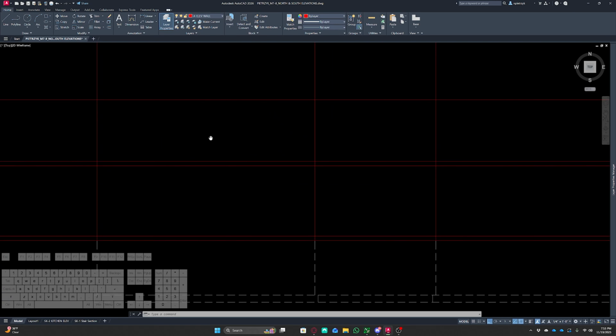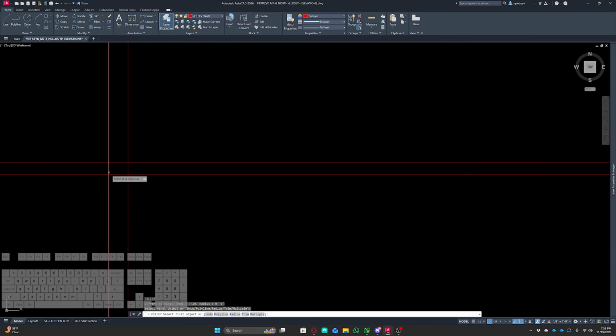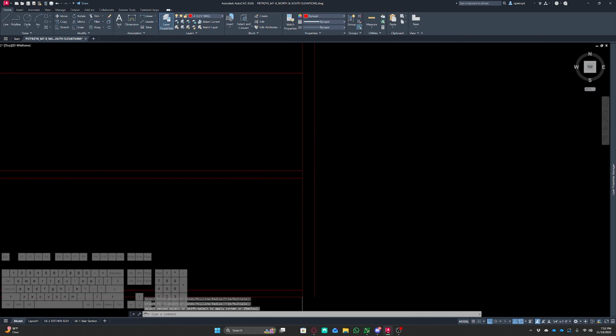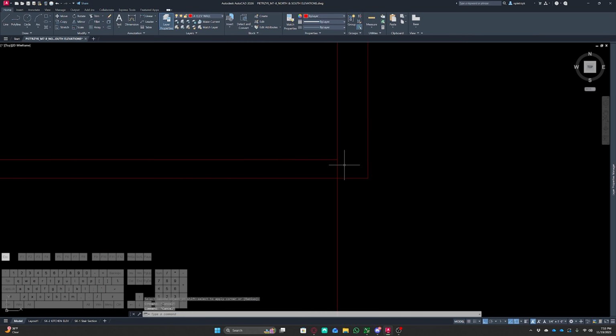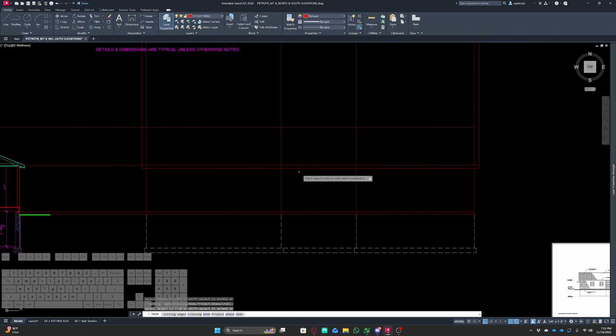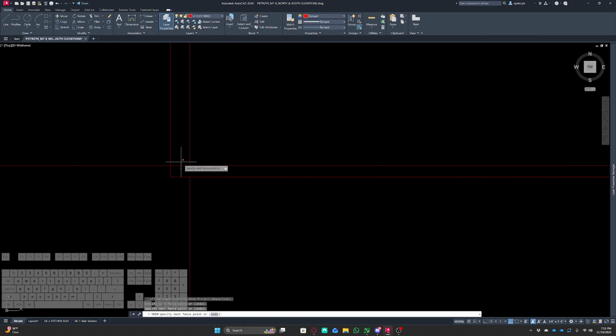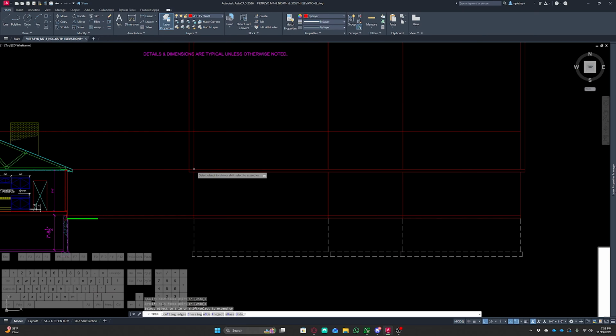So I'm going to do an offset of 1 foot to either side and do a simple fillet there and here. I'm going to extend this line out and do a quick trim, and trim, as well as another trim there. I'll erase this line and this line.